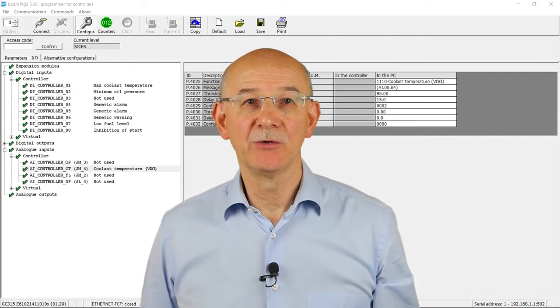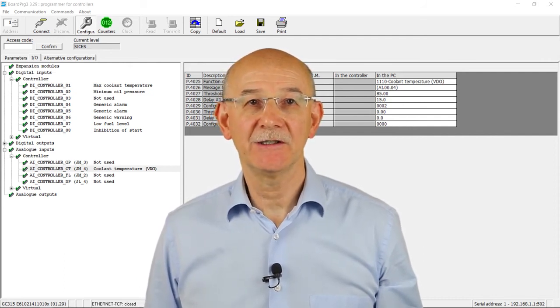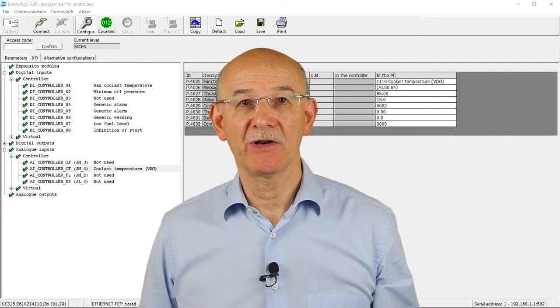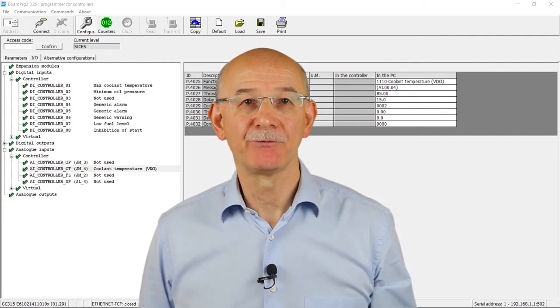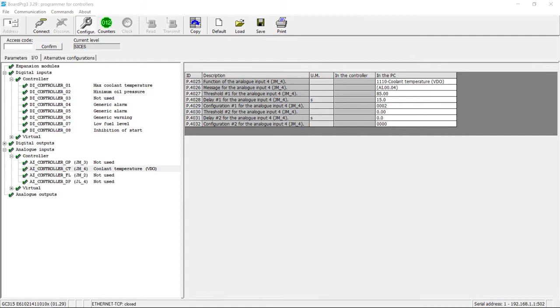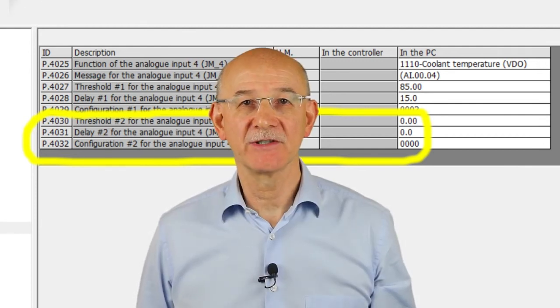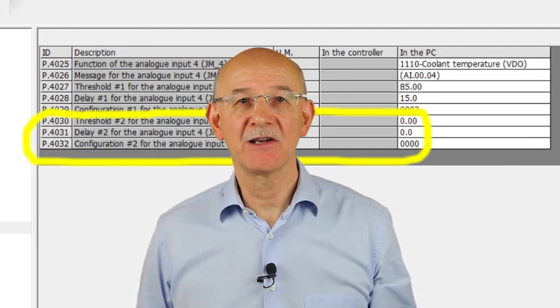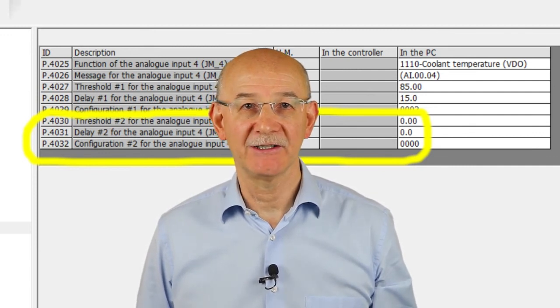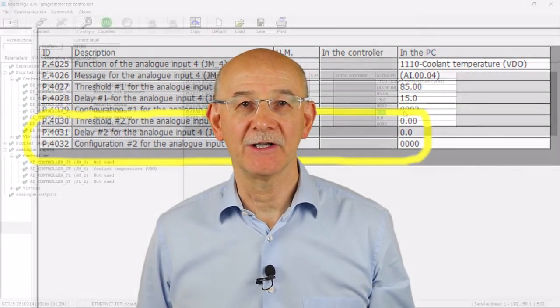Usually, the first configuration table is used to set the internal status and, if required, to activate the anomaly. The remaining 3 parameters set the other threshold for the hysteresis. If the first group sets the status, the second should reset it. If the first has an upward direction, the second should have a downward direction. If the status is not reset, the associated anomaly or output cannot be reset, unless you power off the controller.